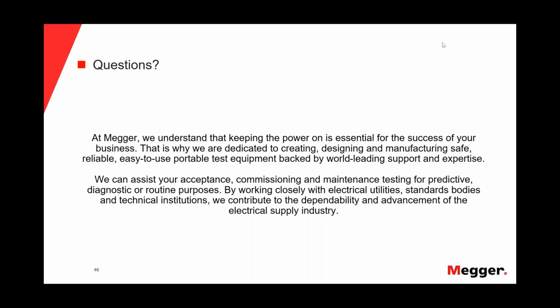Well, it depends. If you have some concern in the way the cable was brought to your facility, if maybe it was not people of your company and you have no idea how they transported the cable from the factory to your facility, it will be good to do a PD test before connecting the splices and the terminations.